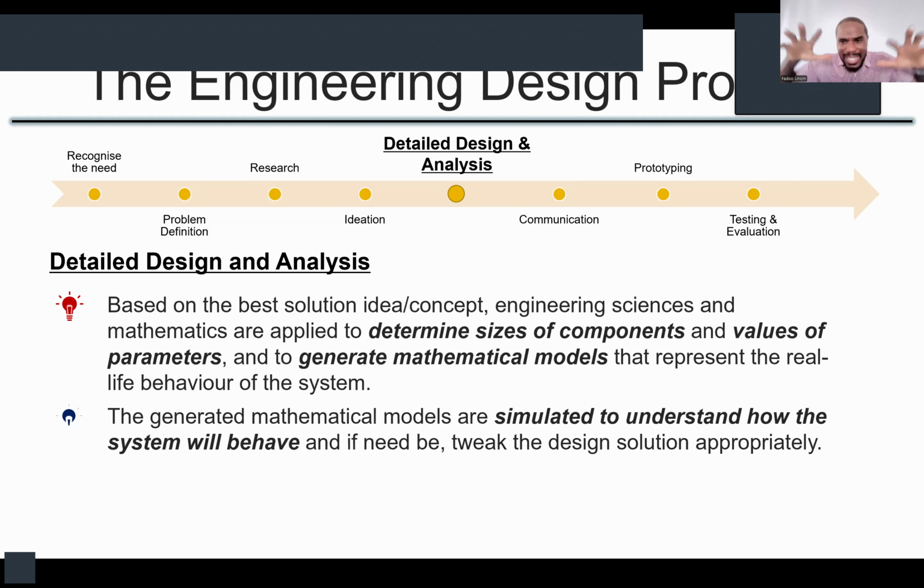This thing is going to carry this amount of load. This thing is going to operate in an environment that gets as high as, let's say, 40 degrees Celsius or 42, 43. Let's test. If the ambient temperature is 42, how much heat gets into my cool chamber? Then you run a thermal analysis to see the heat flow rate across that. You see what happens after some hours. What is now the temperature inside and the temperature outside and all of that. So you gain understanding.